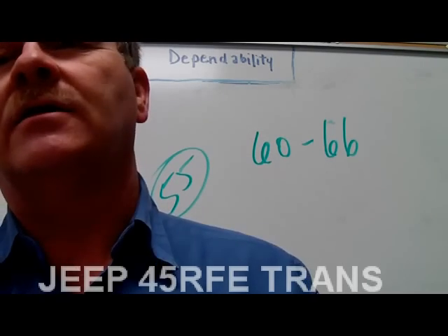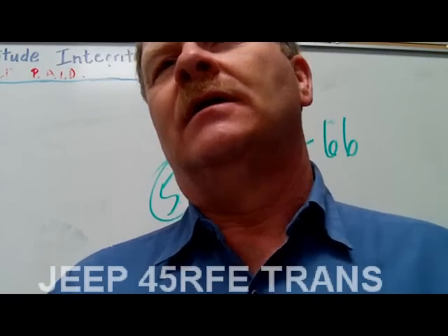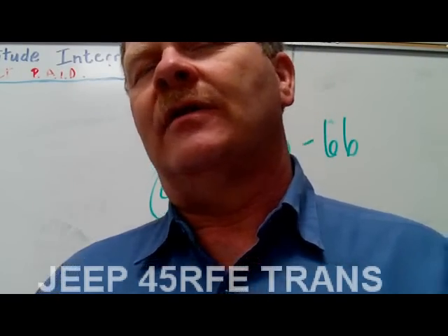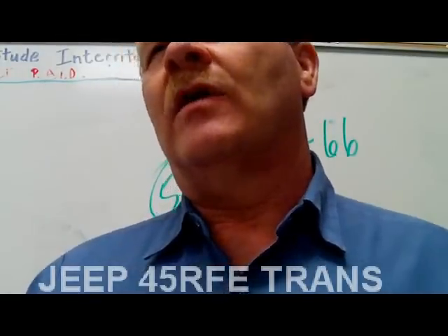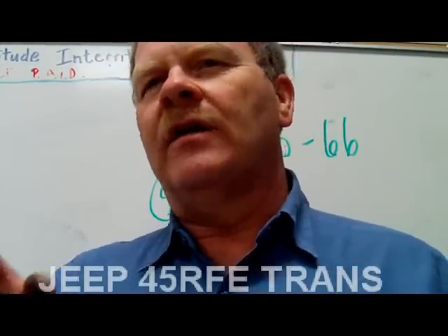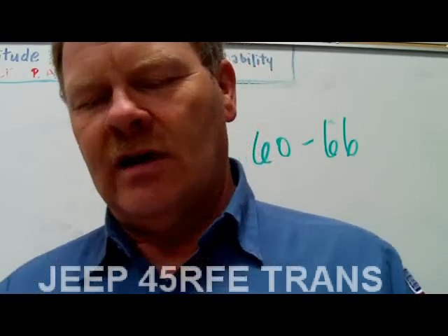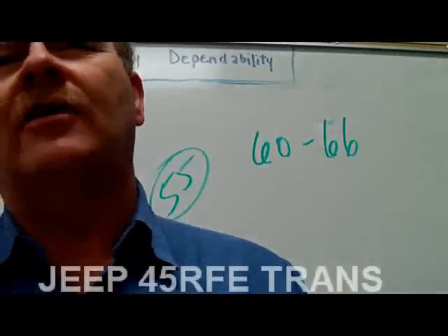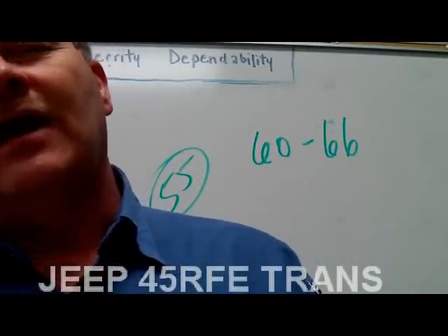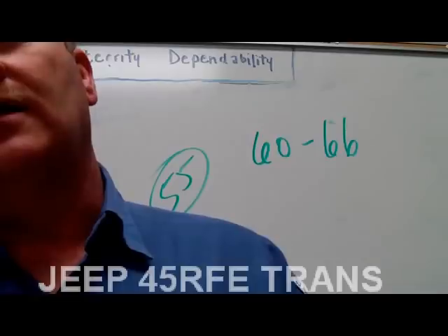Now, what's an overrunning clutch, guys? An overrunning clutch will only hold in one direction. If you're going slower than this thing operates, it's holding in one direction, but as soon as what is being driven is running faster, it overruns. Kind of like a starter drive. A starter drive's got an overrunning clutch. If the starter gear is driving the engine, the overrunning clutch is holding.